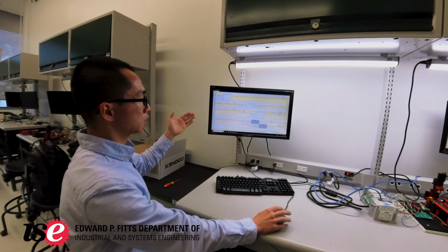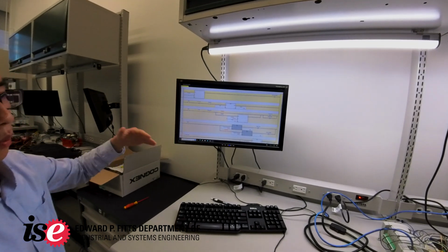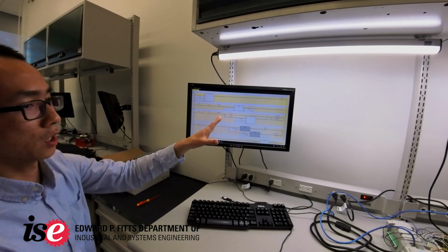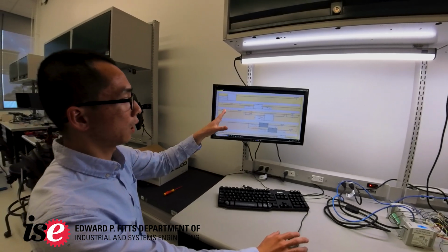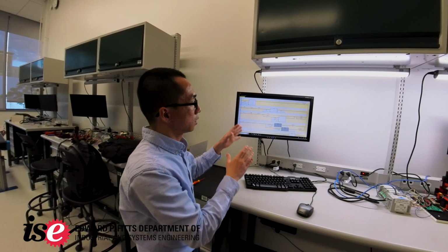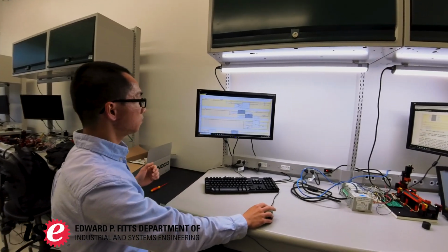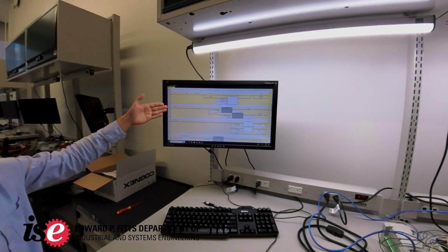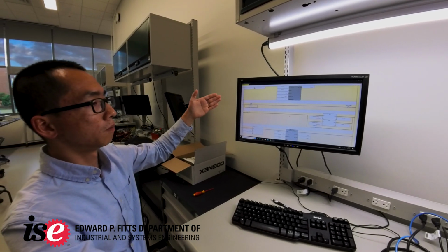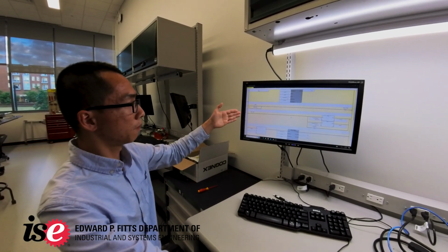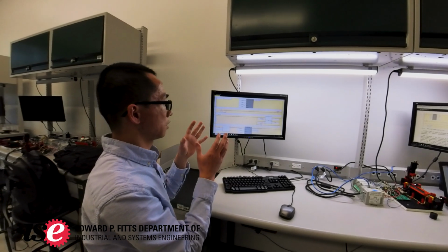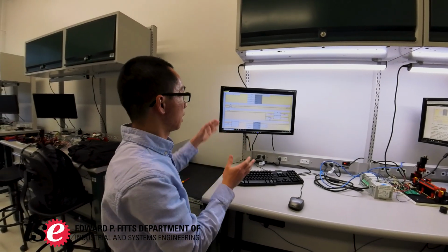Okay, and the next one is there's a timer, and we keep running, and when the timer is greater than 2, it will run the motor and also publish the enable message, which is motor on. But when the time variable is less than 2, it means that we won't run the motor, so the motor will stop. The next 2 lines publish the enable message. And the next 2 lines publish the disable message, which is motor off. So it includes the 2 conditions, which are disable when sensor 2 detects the object, and also the emergency stop.